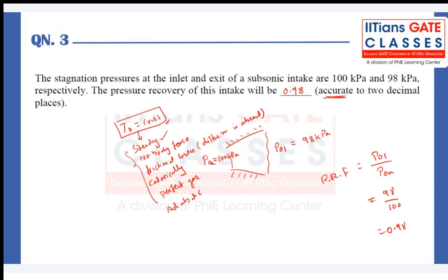I cannot just stop by saying it is the temperature a fluid particle would experience when it comes to rest. It is not the full definition. It's the temperature of the fluid particle when it comes to rest in an adiabatic steady flow field with no body forces involved, for a calorically perfect gas. Then I can say the total temperature is constant in such flows.